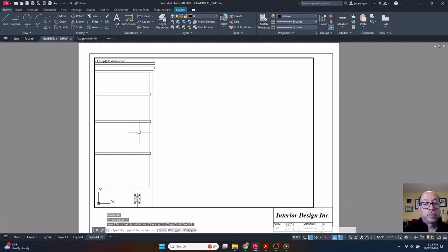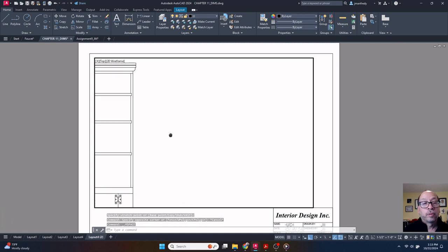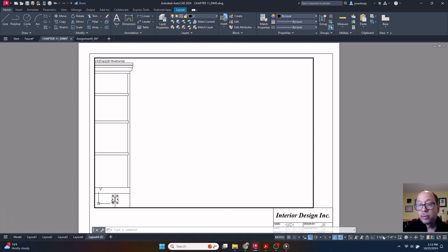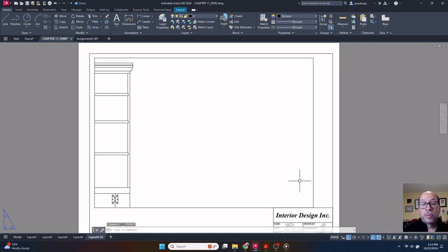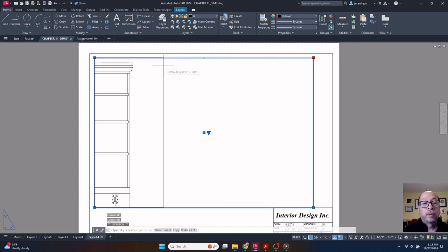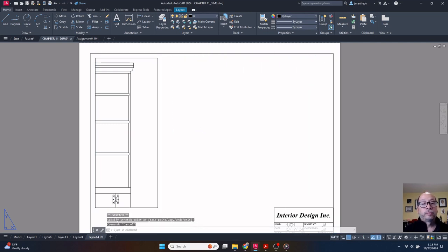So let's say double click. And be very careful not to change the scale. Slide this over till about there. The scale is still 1.5 inches. When you're done with that, go back to paper space and basically focus the window on that portion of the drawing here.